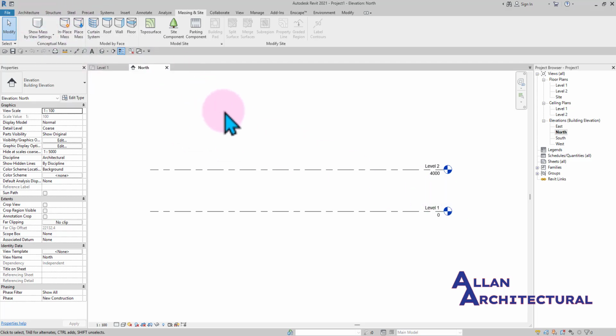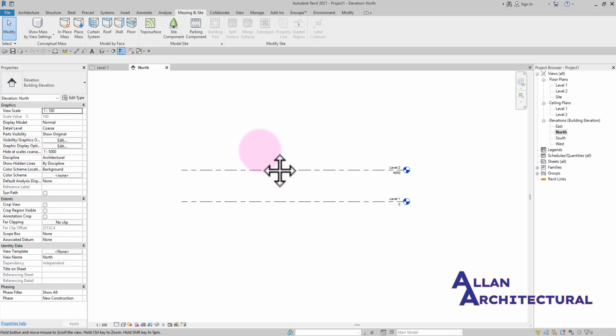All right, so now there are actually two ways you can draw these masses in Revit. There are two ways you can draw those intricate designs. You can either do them inside of your project, or they have their own family editor template, where we can go in there and draw out the shape, and then load that shape into our project here. So it's really very simple.